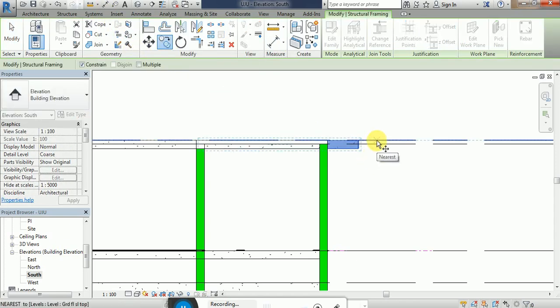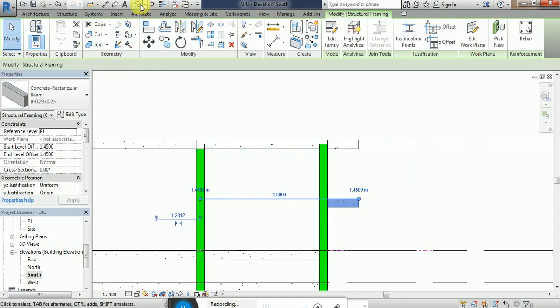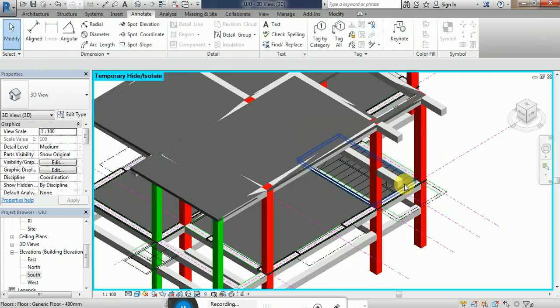Now, if you want to copy these things from here downward, that is rigid because the constraints are there. So first of all, you'll have to turn off that particular constraint, disjoin, and then go to copying. So you can type 1.65. So this will be the landing position. You have got this particular beam here.